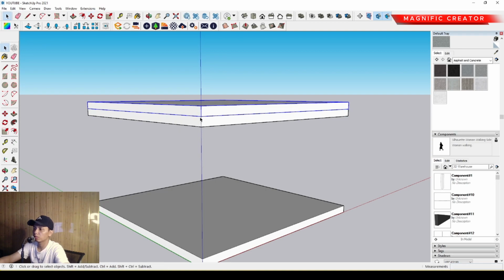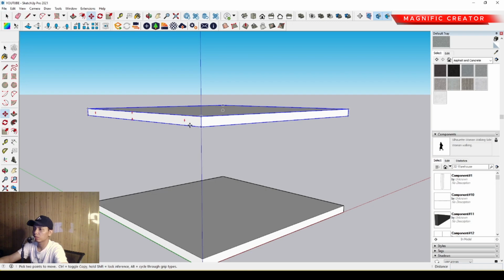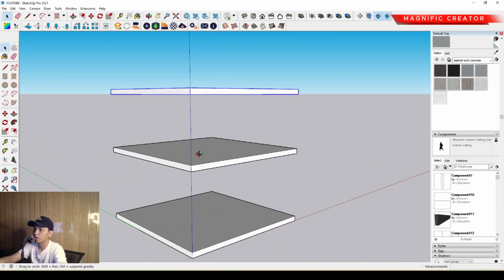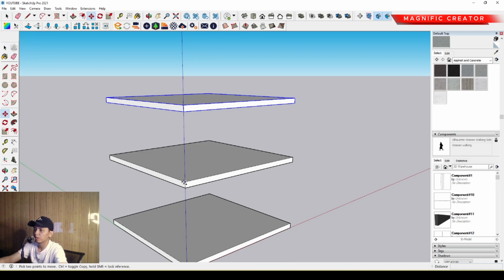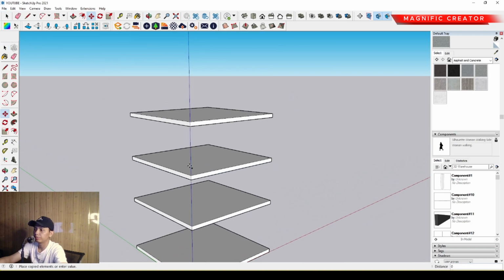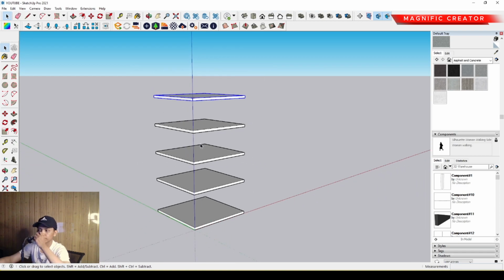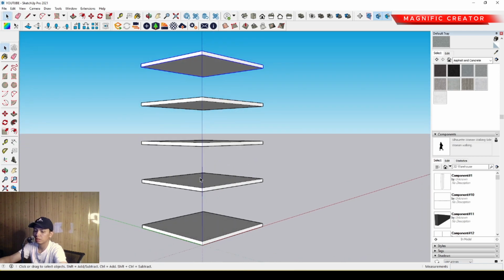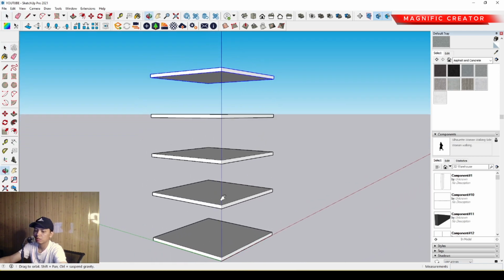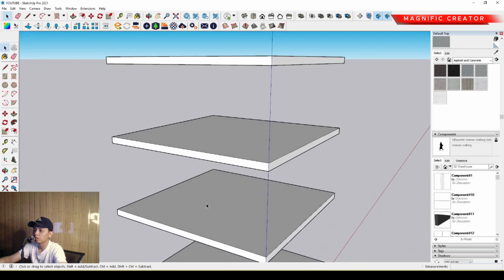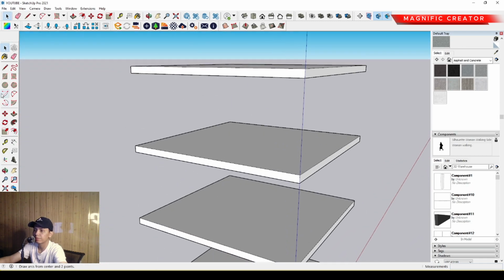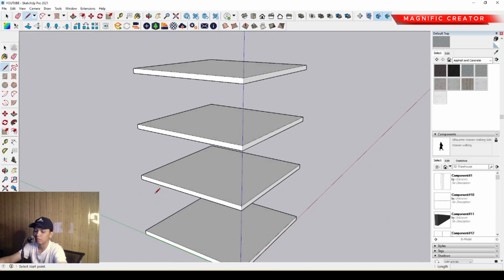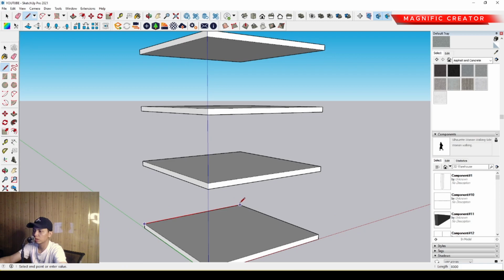We can make the floor to floor 3600 millimeters. So we can duplicate it again to the upper position. Okay, it's just like this, and then we can make the wall. We can make the corner wall over there. We can use the line tool, and we can set this wall anyway.